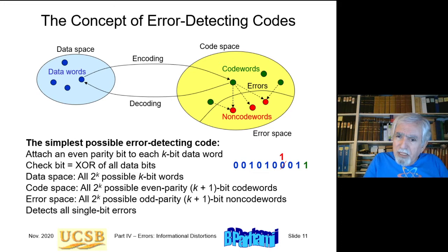So this is a very common code that is used. There's very low redundancy. In other words, you can have 32 data bits and just 1 parity bit. But also it provides very limited protection. If you have 32 data bits, chances of having more than 1 bit error increases. And therefore this single parity bit can provide only limited protection.